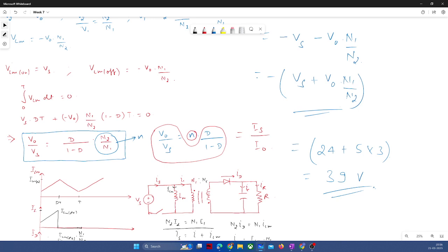Okay, sir, thank you. So, coming back to your question, there are certain things that we need to take care of during the design. Generally, we try to avoid all the spikes in the voltages. Spikes may come because of di by dt. We try to handle it, and if it persists, then we will have to design the switches according to those ratings.